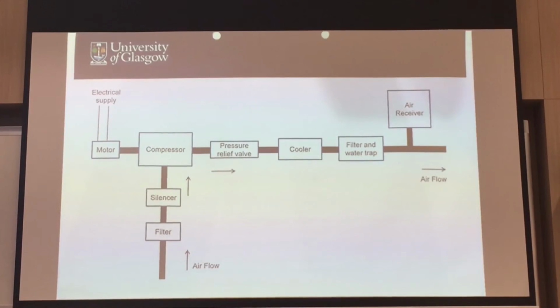You wouldn't be able to run so as to supply you with more pressure, less pressure, no, it's just because there's no feedback. So in that case, you may experience increase or decrease in the pressure. So your pressure relief valve will be able to relieve that increase in pressure out to the atmosphere if there's an overpressure.